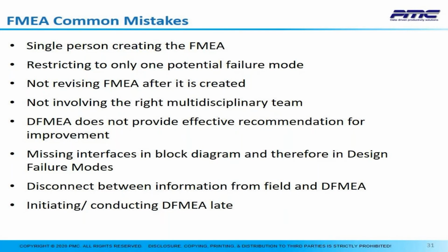DFMEA does not provide effective recommendation for improvement. Design verification plans not modified after recommendations are implemented. Missing interfaces. Disconnect between information from field and the DFMEA. Overanalyzing and underanalyzing effects and the causes, initiating and conducting the DFMEA late. Incorrect procedural sequence or scoping of DFMEA.